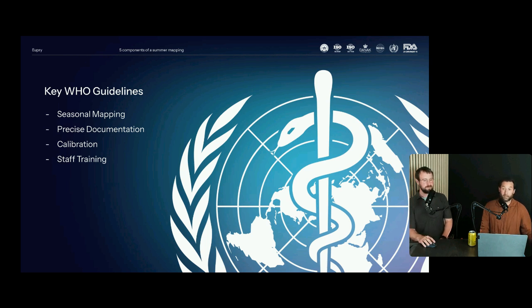Exactly. A key element, as I mentioned before, is the calibration of the devices. They should be calibrated for the exercise. Sometimes some of our customers also require an end or exit calibration, just to double check if there has been any drift. And here you should usually be in accordance with ISO 17025 when it comes to calibration certificates, etc. Absolutely. Yeah. So just moving on a bit.